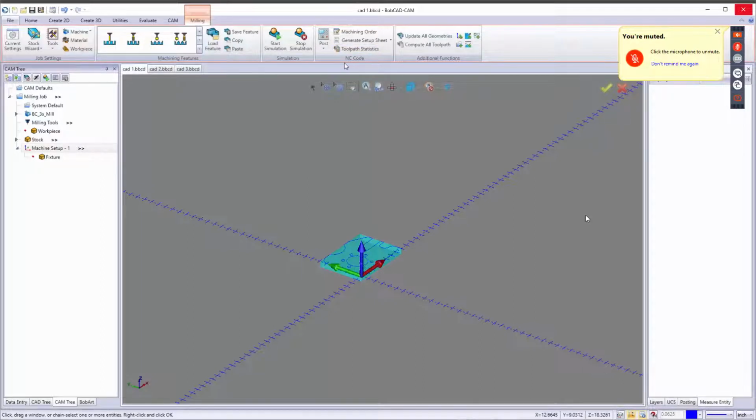Moving over to the NC editor, we have our post. And then if you hit the drop down here, you have post and save as. Now, you'll hear me say in trainings, it doesn't matter if it's online, seminars, on-sites, and houses here, I always say hit the little control box. That means push that button right there. That's a little control box icon.